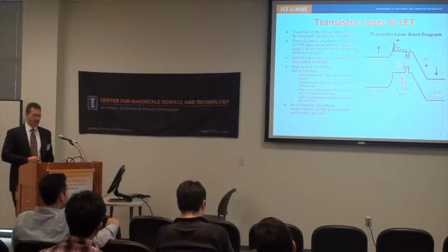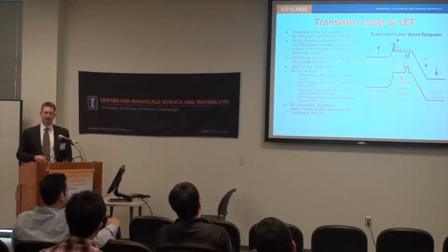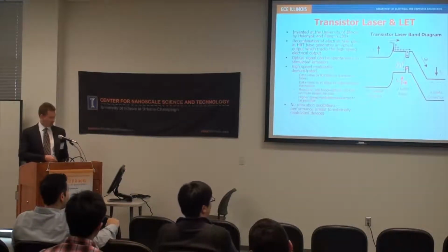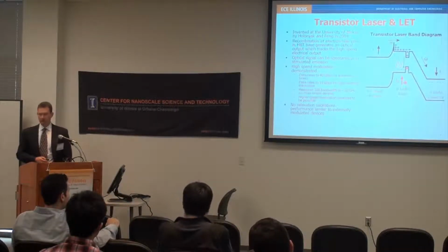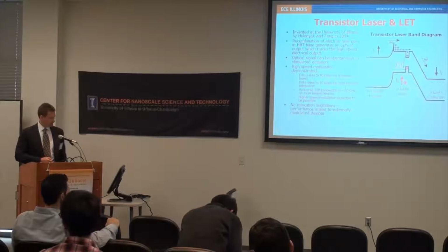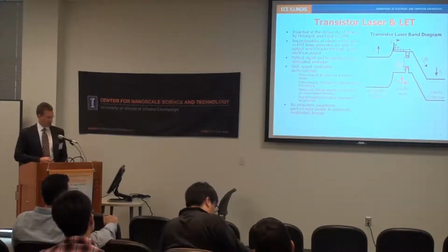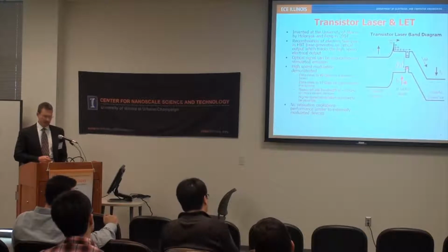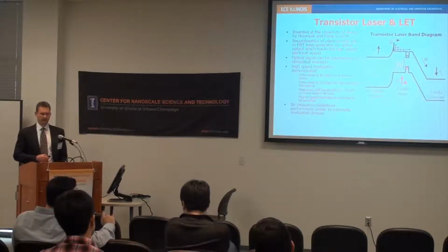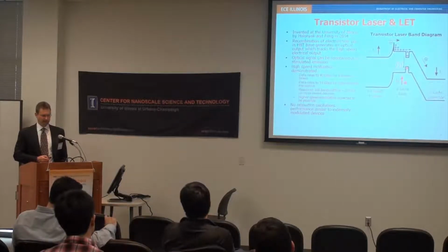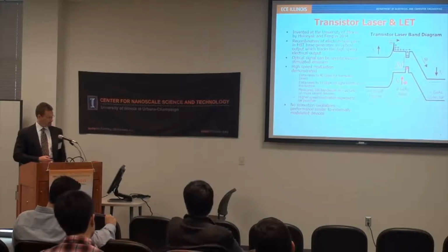As a consequence, you have a device that can be modulated to very high speeds, and they've demonstrated for transistor lasers up to about 40 gigabits per second, relaxation oscillation free, with no need for external modulation. So it's a very interesting device, still early in its development or understanding of what can be done with it.